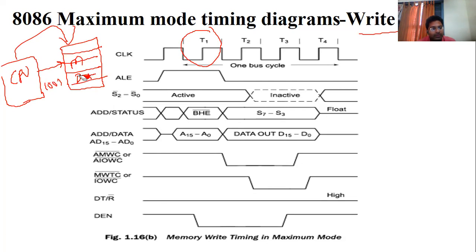You know that for this address there is some data also, because the microprocessor cannot erase data. It can only overwrite data, so a previous data is already available. Whatever data you send to the memory on that address is just overwritten. Remember, the T2 clock period is required to convert that address to the data.